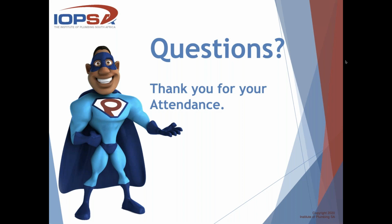I think the reason guys haven't been doing it is that where I live specifically, the municipal pressure rushes up to 9 bars. So yes, you have much more than the working pressure. So the guys are neglecting pressure testing because they know that the pressure is very high, so they don't test it. But this is what the standard says.